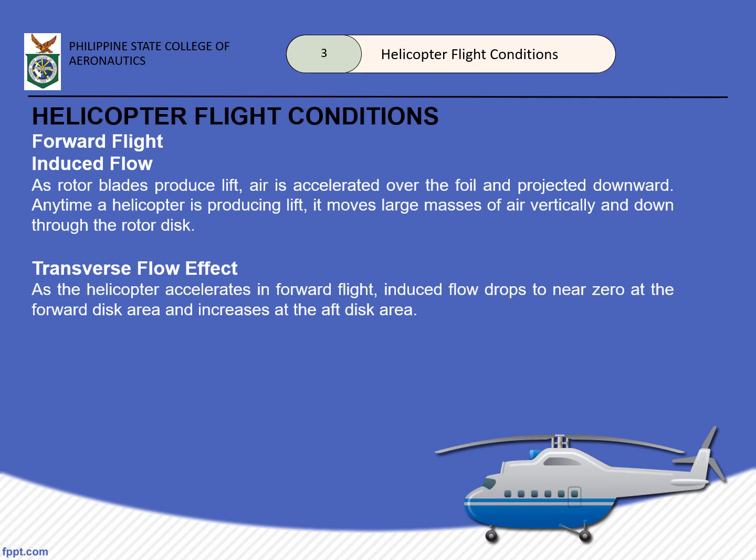We also have the induced flow and transverse flow effect. Induced flow is also referred to as downwash. It affects the rotational relative wind and has a tendency of decreasing our angle of attack, then, of course, also affecting our efficiency. And our transverse flow effect is the rolling tendency due to lift difference of forward and aft portion of the rotor disc. Acting as a gyroscope, the maximum effect occurs 90 degrees in the direction of our rotation.